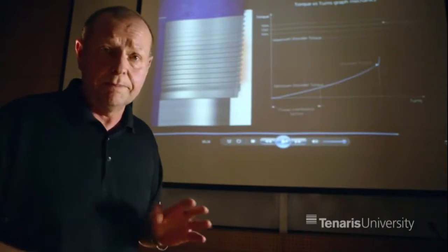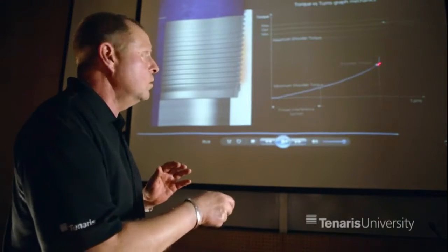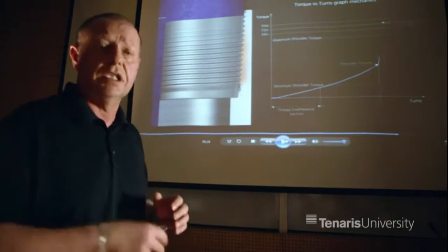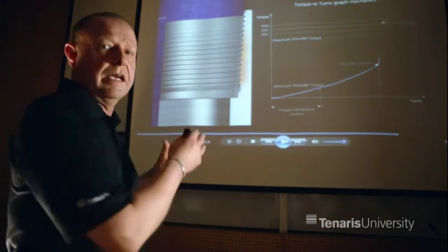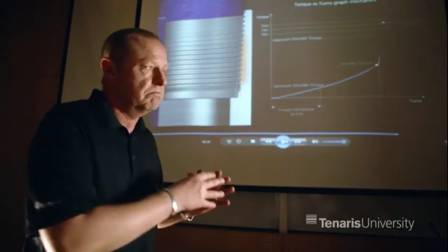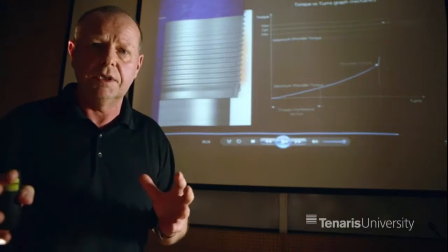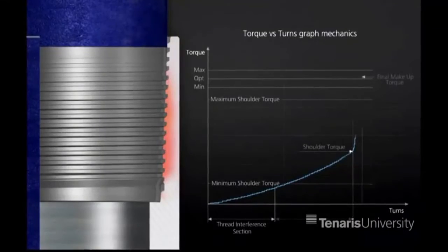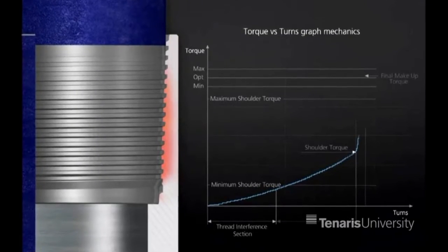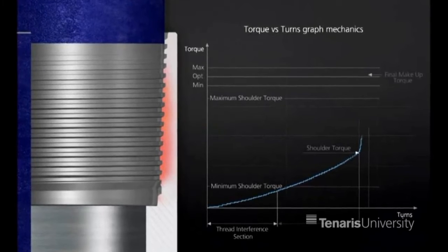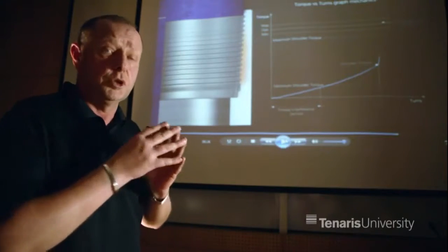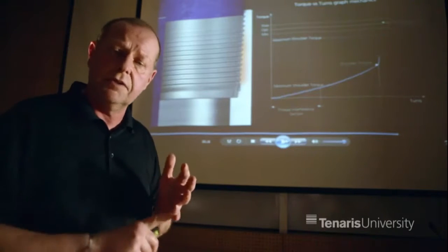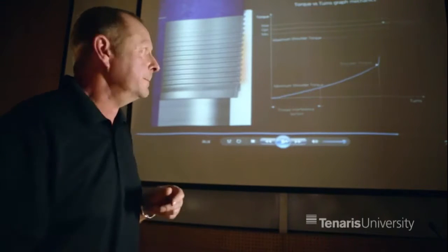Within this build slope you need no irregular discontinuities. It needs to be a fairly smooth gradual build process. That's how this type of connection works. There are other graphs and other types of connections which will work differently, but this one, which is a fairly standard, most commonly used type of connection, the threaded and coupled shoulder connection, will have this type of build slope. A thread part and then a thread and seal part.